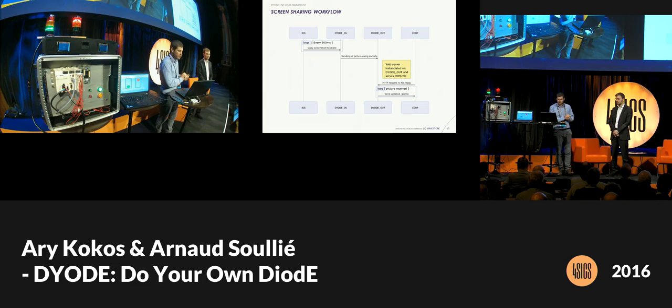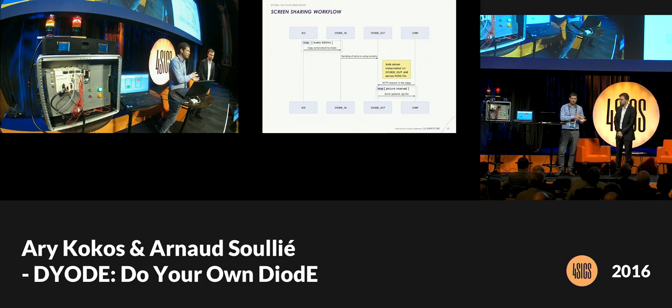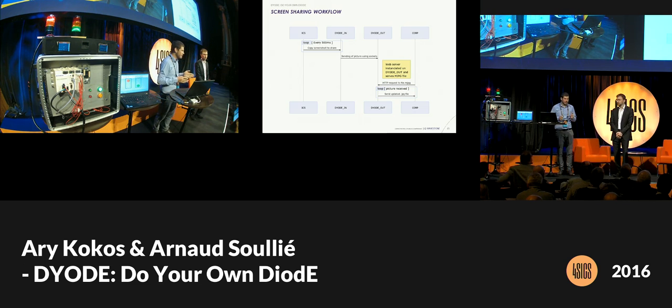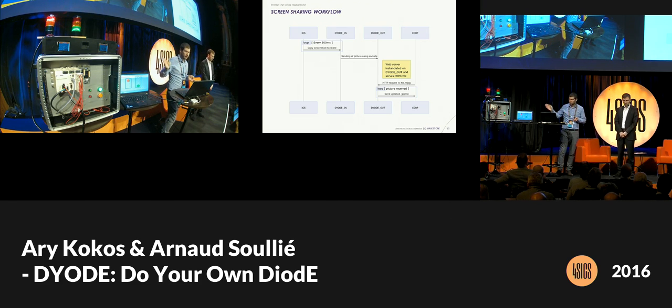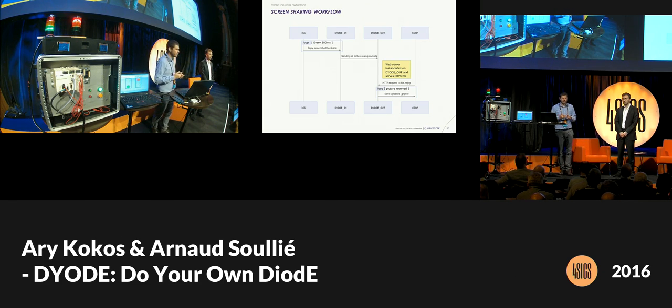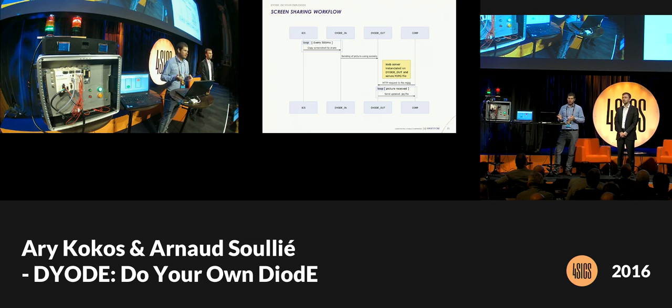Last thing, the screen sharing. As mentioned, PowerShell script on the SCADA PC that will send 2 screenshots per second on a network share. Then, again, we send that over a UDP connection to the output counterpart. And then we use a technique that's used mainly by webcams, I think. It's a web server that serves an mJPEG file. So that means the client sends one request, and then the web server just keeps sending new pictures every 500 milliseconds, which gives the impression of a video.